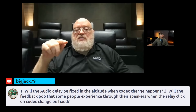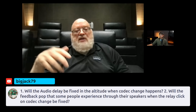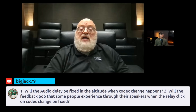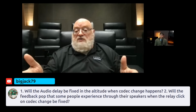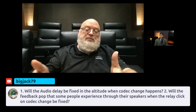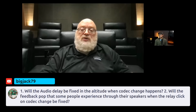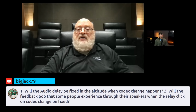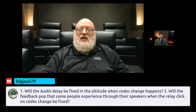We don't do that because in the part of the market we exist in, a lot of our customers, maybe today, maybe in the future, will want to have a Lumagen or a MadVR or some other video processor. And so our HDMI board is specifically designed to be bit perfect as far as video is concerned. It just passes it through. We peel off the audio stuff that we do such a good job with, but the video information just goes straight through with no change whatsoever. So every single time something changes, your TV will probably say, let me check to make sure everything is still kosher. And that just slows things down.